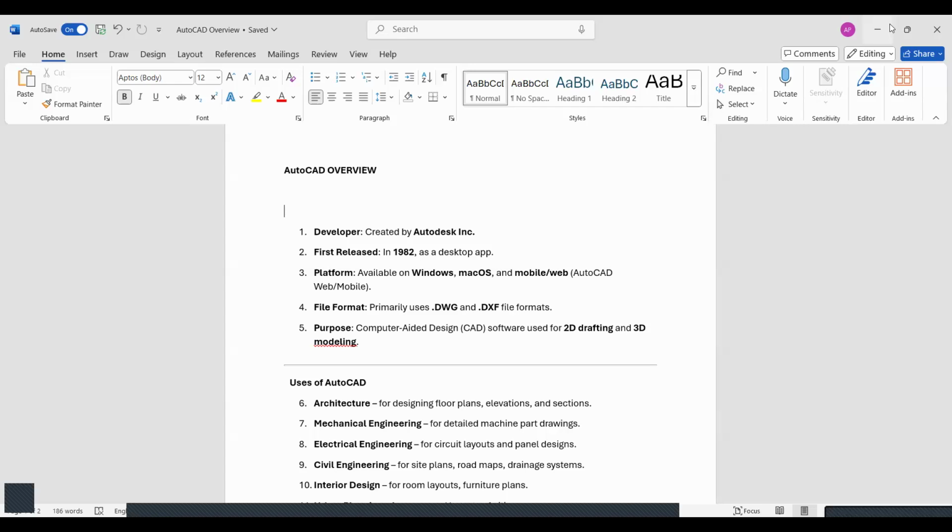Now, what is the second part? Suppose you are dealing with this circle, and you want to isolate these circles, so what do you do? Just select similar. There is a command of isolation: hide isolation and isolate. If you want to work only on these circles, you just isolate it. As you can see, all the circles got highlighted and the rest of the drawing got hidden. If you want to end this, you can end it like this.